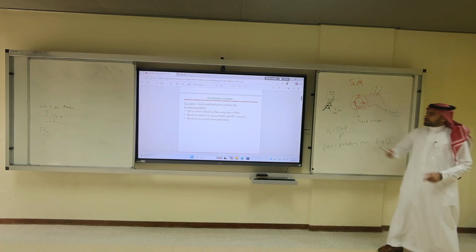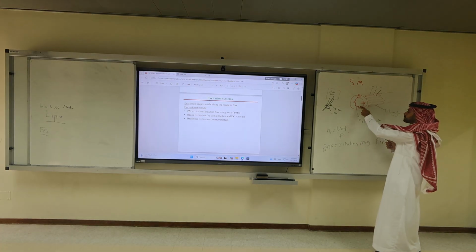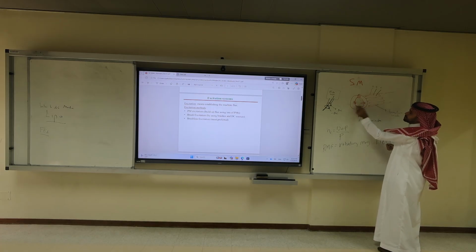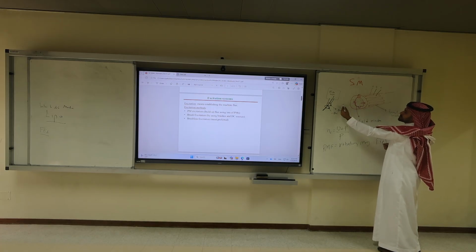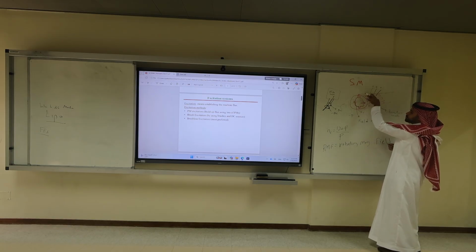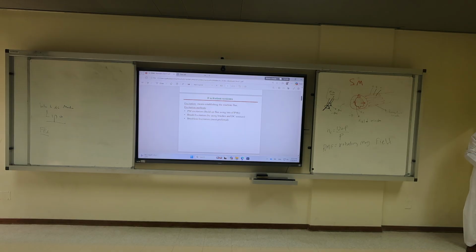So, in order to connect the rotor winding in this figure, I have the shaft here. This is the shaft. I need to put slip rings here, positive, negative. And then some of the coils will get positive, some of the coils will get negative. And then I create the flux from positive to negative.